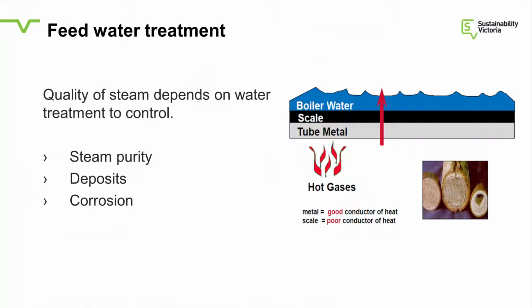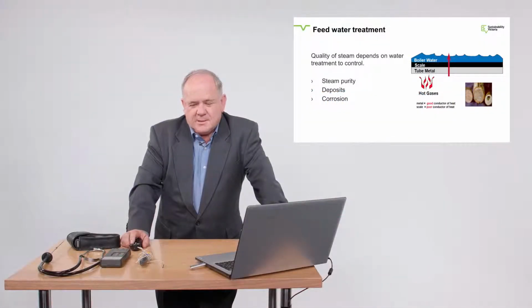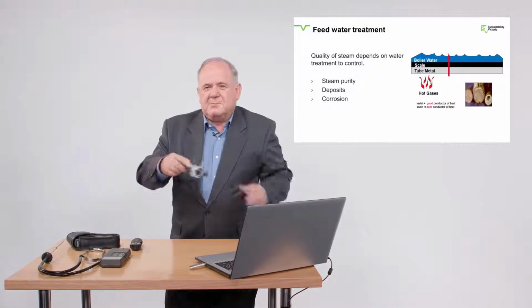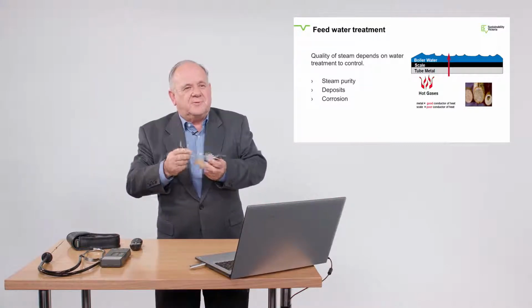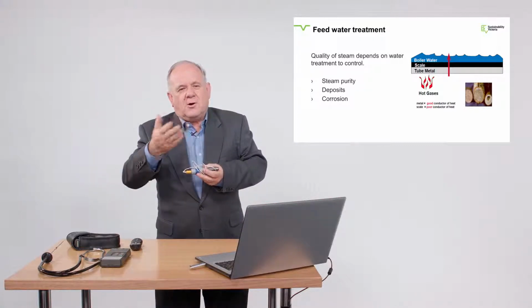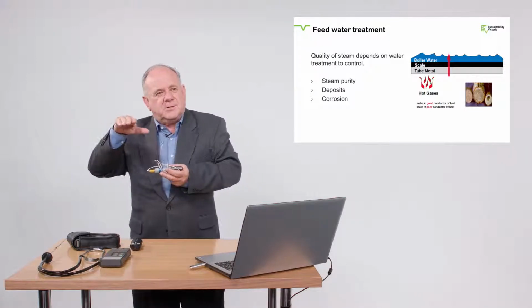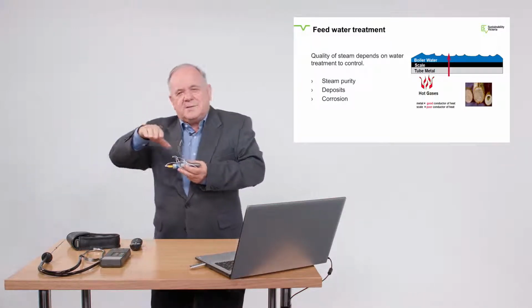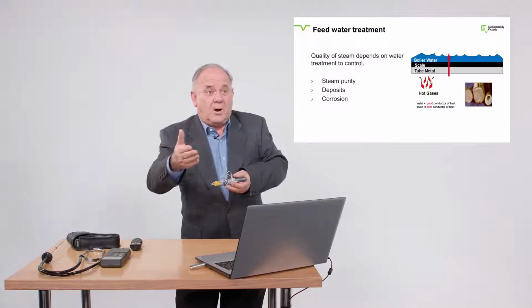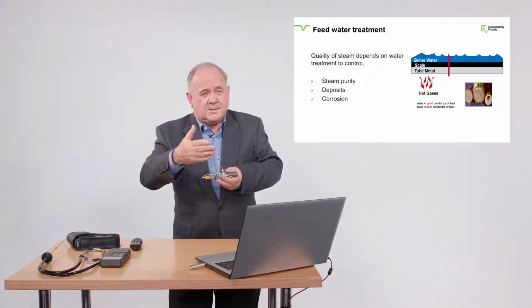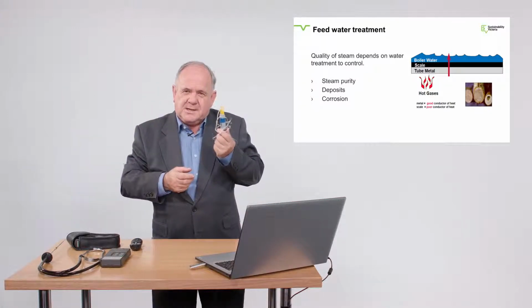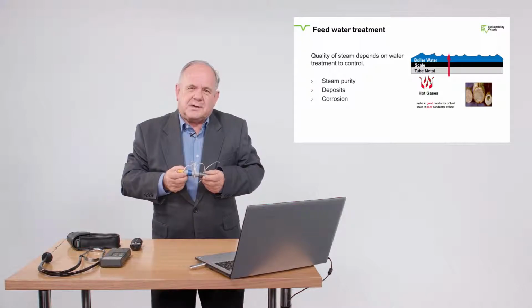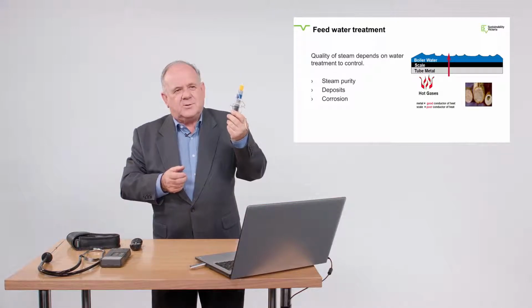The way to check that again is the flue temperature. It's good to have even a little basic instrument like this. This is a little logger that measures temperature. You can pop one of these into the flue of the boiler, and at high fire you should expect this temperature to be a certain level. If it's higher, if either the water treatment or bypass of combustion products are starting to occur, the temperature will increase. So that's a good symptom, or a check, to see if there's something starting to go wrong with the boiler. To give you an idea, these things are $120 each.